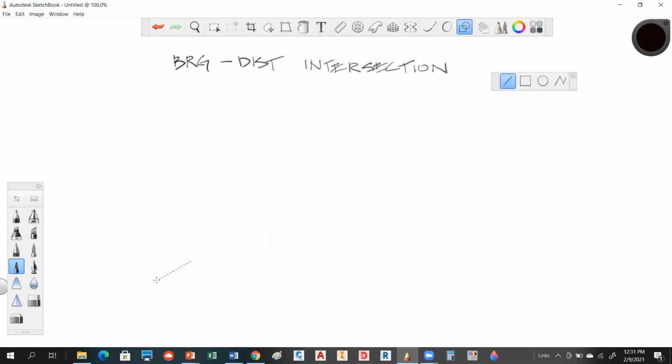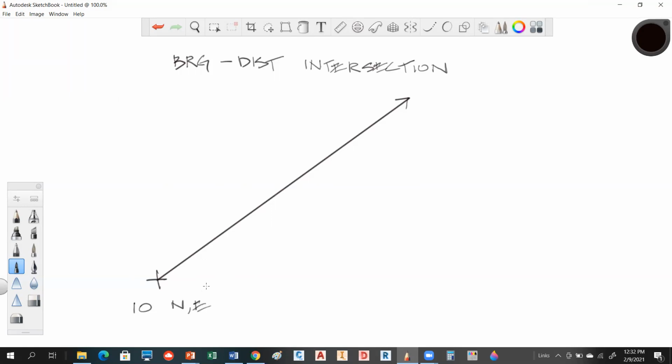But let's say you have a bearing right here. So this is a point. You know this point. Let's say again, you're maybe at point 10. You know this point's northing and easting, and you know this line's bearing or azimuth. You could use either one; I just choose to use that. So we know the bearing on that line. So you have another known point.